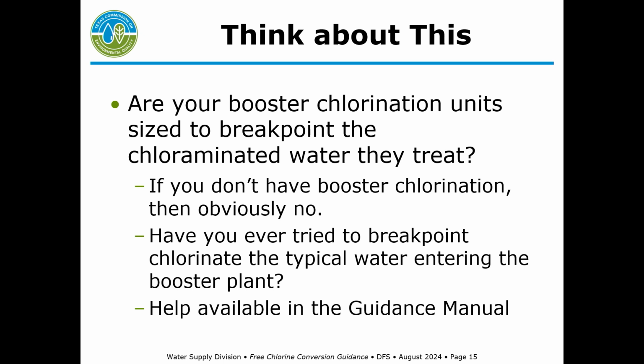you have to consider: if you don't have any booster chlorination, then no, this isn't going to be a problem. But if you are going to try to breakpoint with your booster disinfection station, have you ever tried to do that before to see if you can actually accomplish it? Again, your chlorine injectors, if they're just sized for booster disinfection, may not be big enough to actually breakpoint chlorinate the water. There's some help in the appendix of the guidance manual that takes you step by step through how to figure out how much chlorine injection capacity you will need for your particular water.